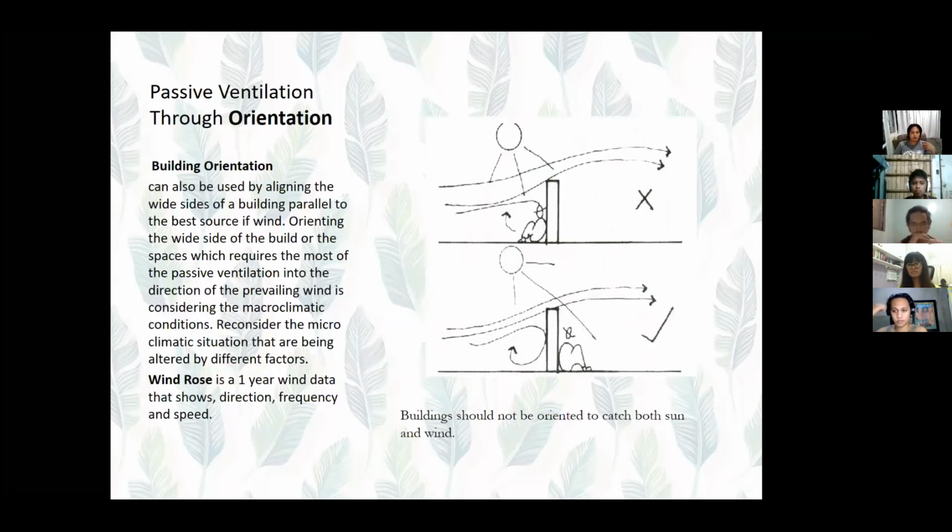So, first is you gotta do building orientation. Kung nagkataon na pantay, east-west orientation plus the orientation ng size ng building in terms of wind, okay lang. But most of the time, the shorter side is supposedly the east-west side, and the longer side is on the prevailing winds, which is in the northeast. Okay? So with that, you need to balance that one out. Okay lang na siya medyo mainitan, as long as well-ventilated.